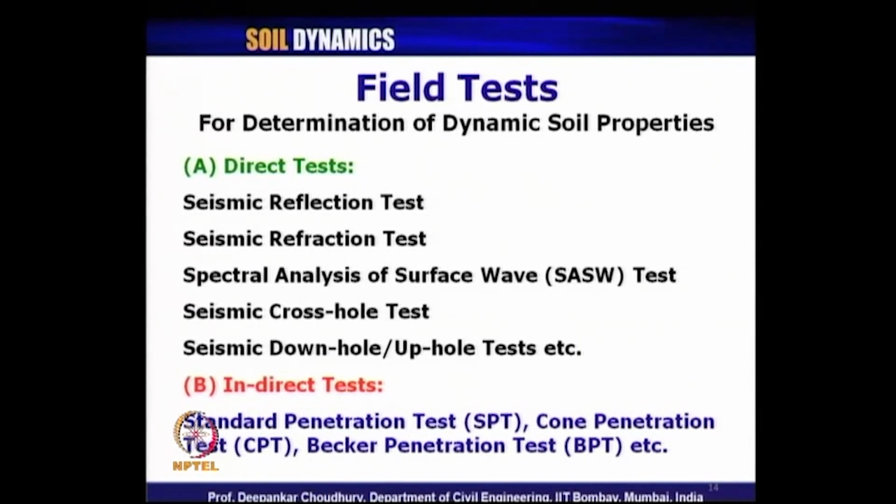And what are the common indirect tests? Like SPT, that is standard penetration test, cone penetration test or CPT, Becker penetration test BPT, vane shear test, etc. As you know, these are the common field tests for static condition also. So, to determine the static soil properties, these are the tests.